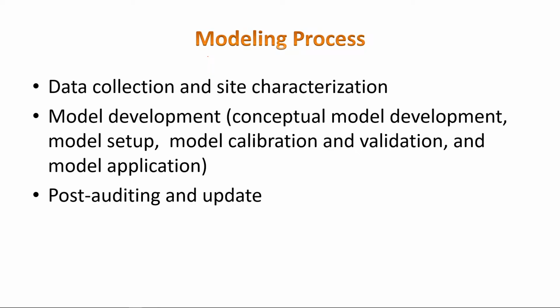Now you took a course like this, you have this knowledge, and then you are assigned something like this. Then you start your data collection and site characterization. Then you do your model development: conceptual model development, model setup, model calibration and validation, model application, and then you do post auditing and you update your solution.